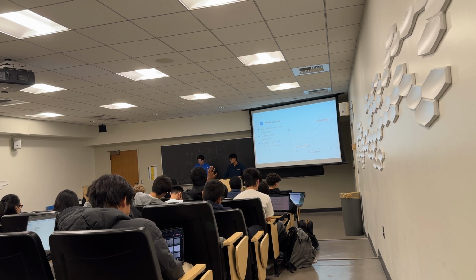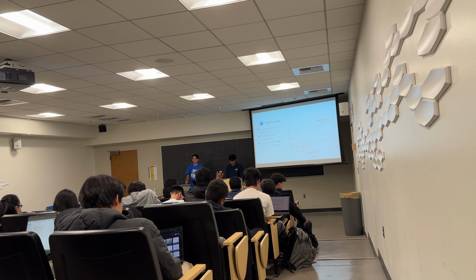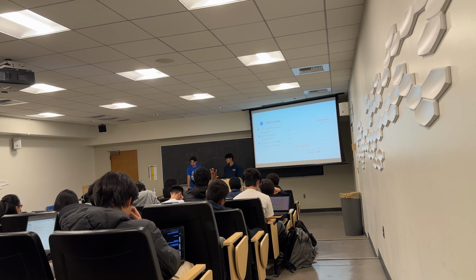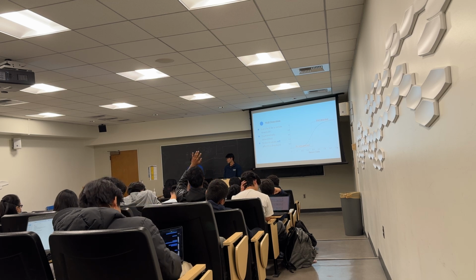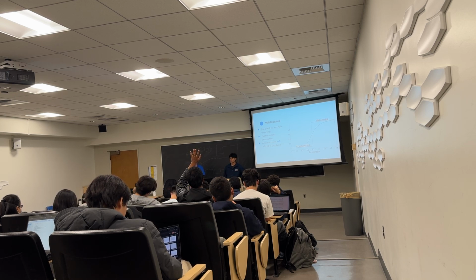Here's how you actually do it. You place your mouse in the maze, connect your ST-Link on the back of it, and run the debugger. I don't know if you've done the motor one yet, but if you had to run the live expressions, you can read what the IR values are live. Then you say, okay, it reads like 2000 at this spot, and you pick a threshold like 1900. Anything greater than 1900, I'm next to a wall.